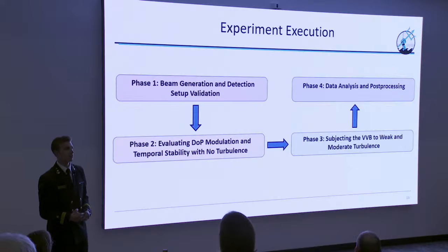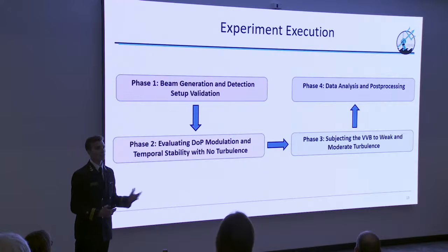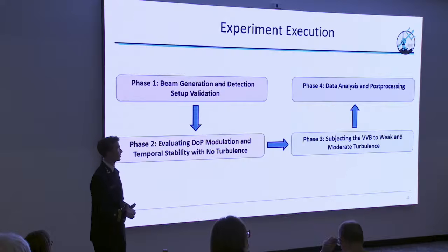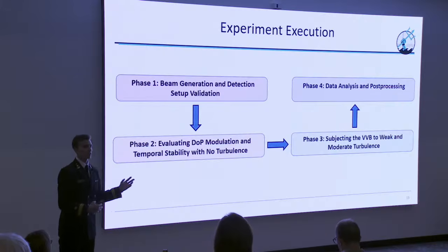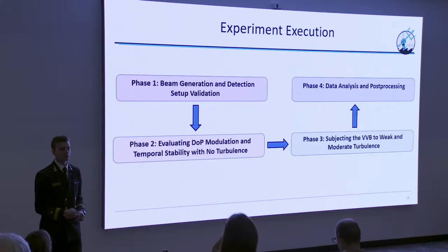After this, we were able to move on to turbulence testing, so we propagated these beams through weak and moderate turbulence. And after a lot of data processing, data wrangling, and some nice MATLAB code, we were able to analyze this data and see how exactly our vector vortex beams were affected by our optical turbulence.